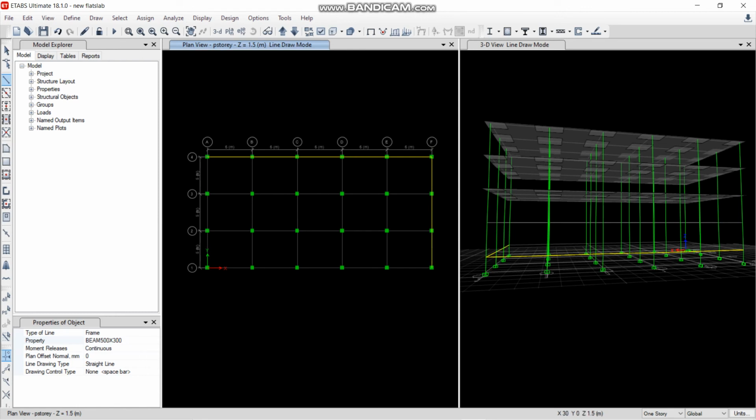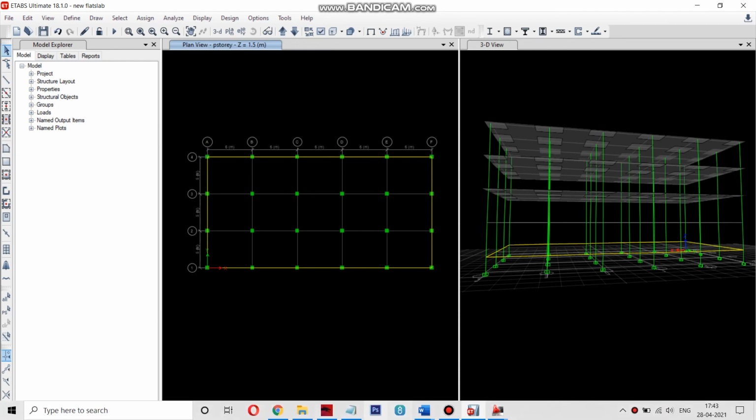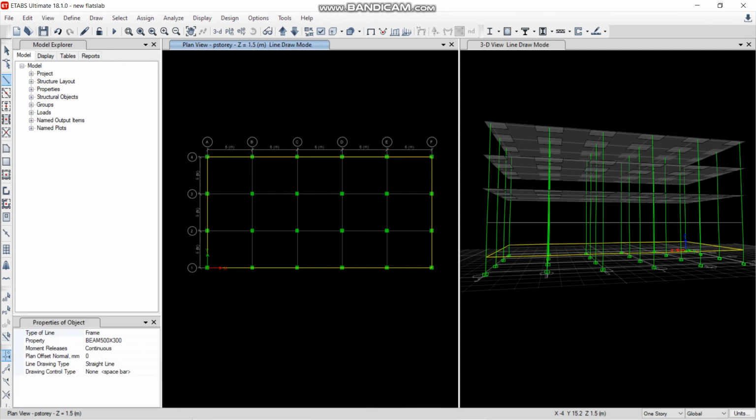This is a slow process. Even if it's a large structure, you cannot make use of this procedure because it's really time consuming. So the next step is I'll show you. Select one beam and go straight to the end. Okay, now that's a single beam. At the joints or at the columns, the beam isn't fixed, it's just pinned, in both horizontal and vertical directions of the model.